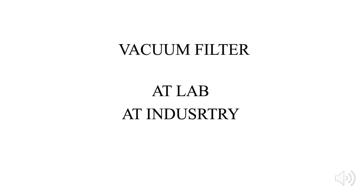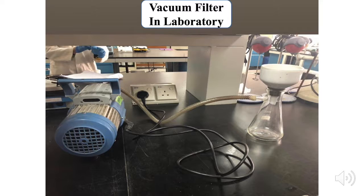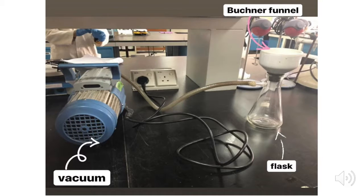So, I will tell about the equipment that is used in solid-liquid separation. Vacuum filtration is the equipment that is widely used in lab and industry. Firstly, this is the example of vacuum filtration that is used in lab. It consists of Buchner funnel, flask, and vacuum. For the vacuum to operate, the mixture of solid and liquid is poured through a filter paper in a Buchner funnel. Then, the solid is trapped by the filter and the liquid is drawn through the funnel into the flask below by a vacuum.